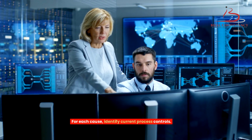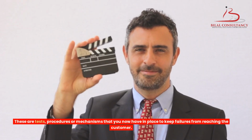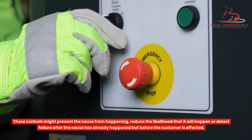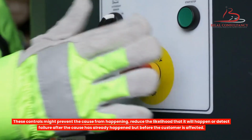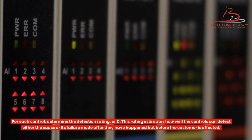For each cause, identify current process controls. These are tests, procedures or mechanisms that you now have in place to keep failures from reaching the customer. These controls might prevent the cause from happening, reduce the likelihood that it will happen, or detect failure after the cause has already happened but before the customer is affected. For each control, determine the detection rating, or D.